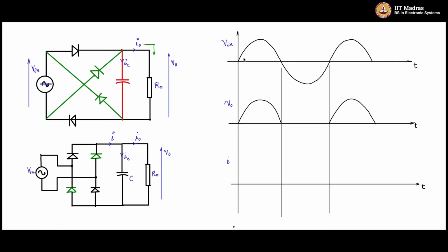If you see in the half wave rectification circuit, the negative portion was not utilized. Now in the full bridge circuit, the negative portion is also getting rectified and utilized. So this also will become part of the output for filtering purposes.